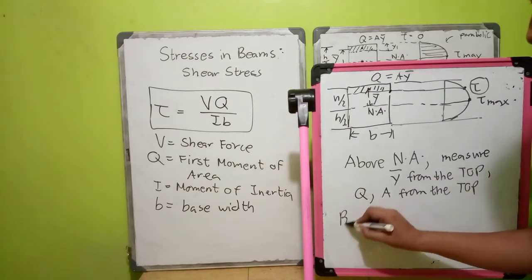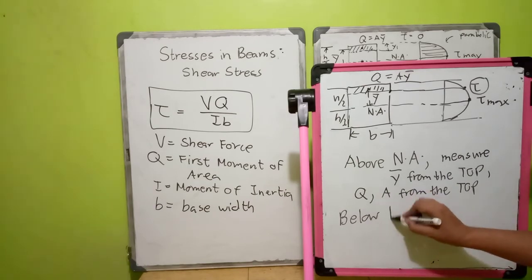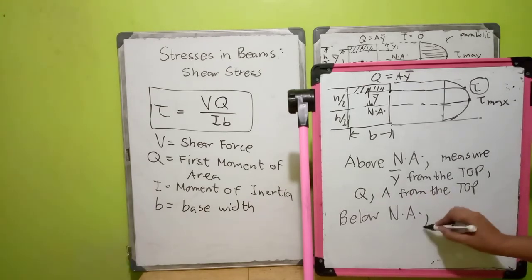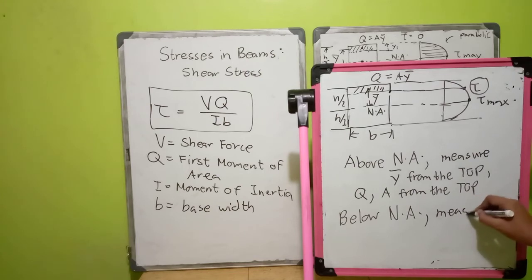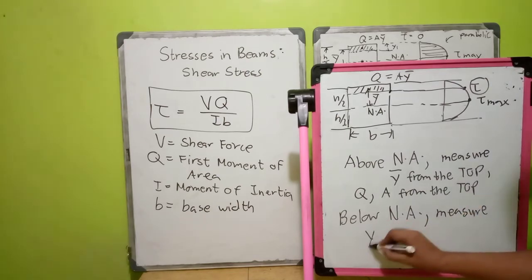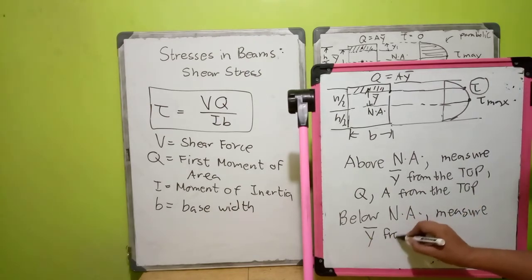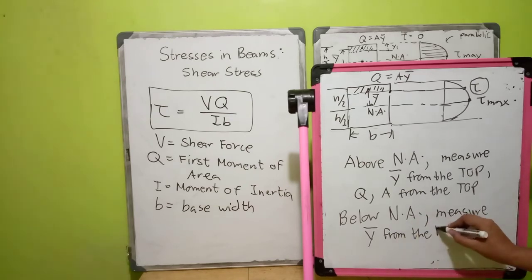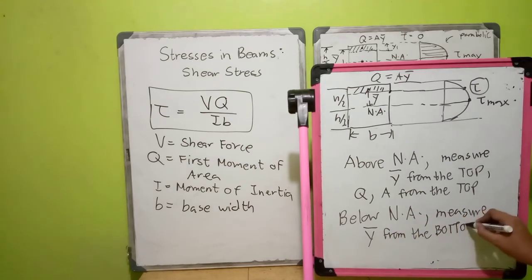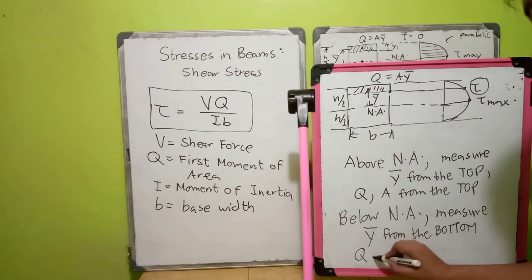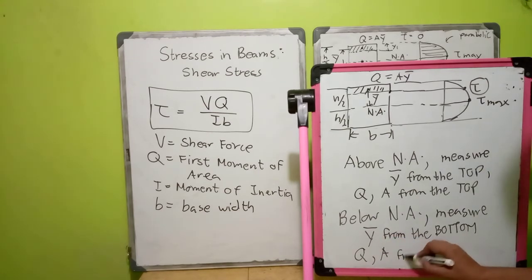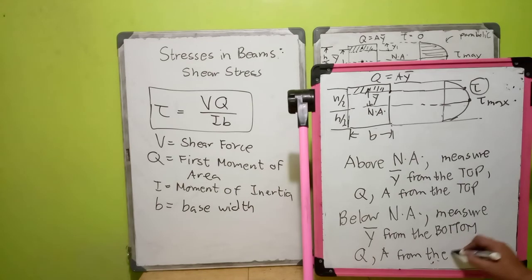And if it is below the neutral axis, measure Y bar from the bottom. And also your Q and A, you compute from the bottom also, okay?